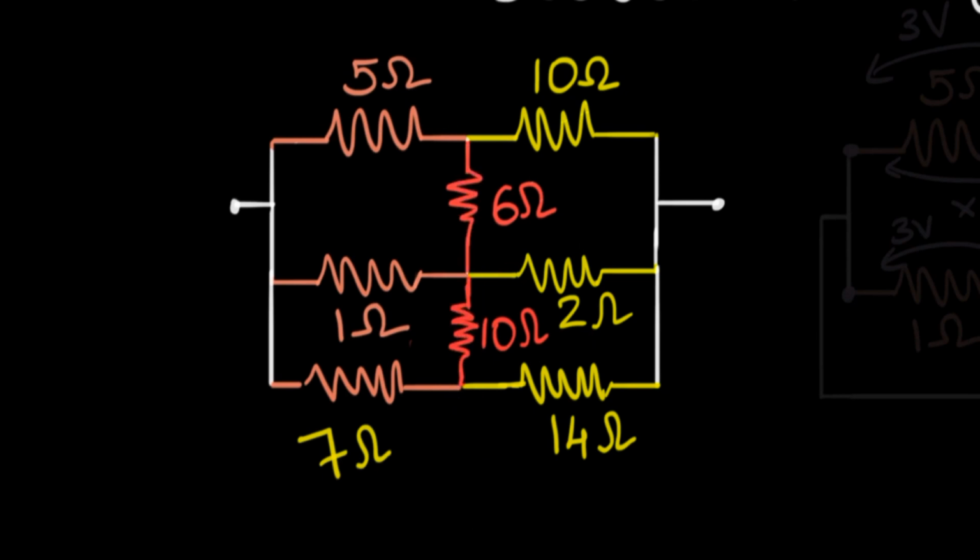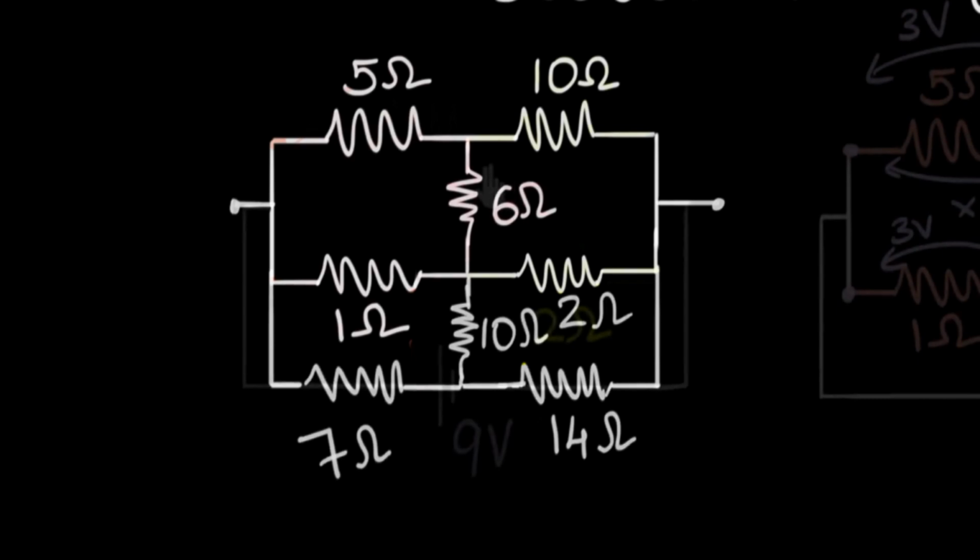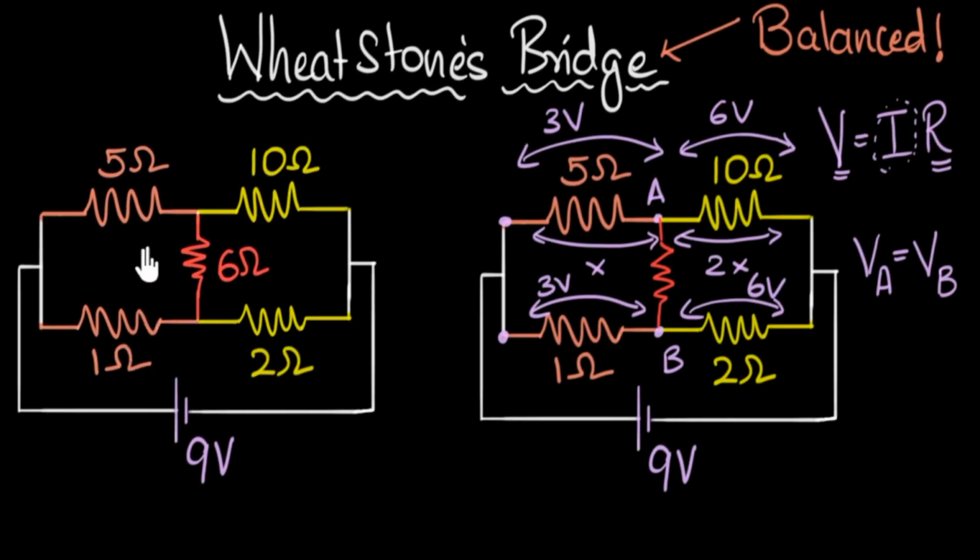All right. Again, notice we can use the same logic. If you forget about these resistors in between, then the voltage should get divided equally because, again, they have the same ratio, 1:2, 1:2, 1:2. And therefore, the voltages here, here, and here must be the same, so no current will flow over here. And so you can neglect this and you can solve this circuit. If I hadn't given you the color coding, just look at how complex this looks. Typical competitive exams problem. Looks very complex, but by using the same logic of Wheatstone's network, you can solve it.